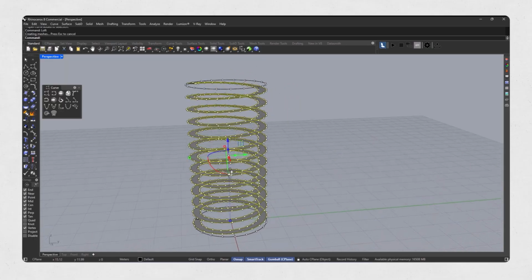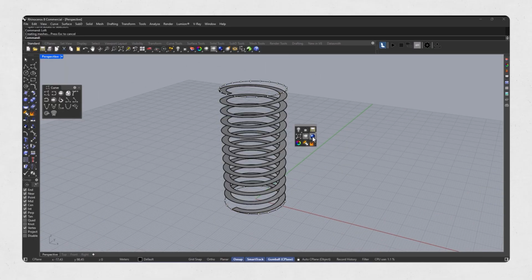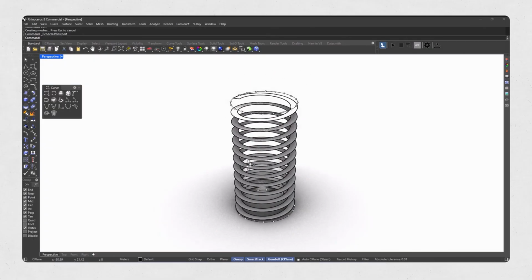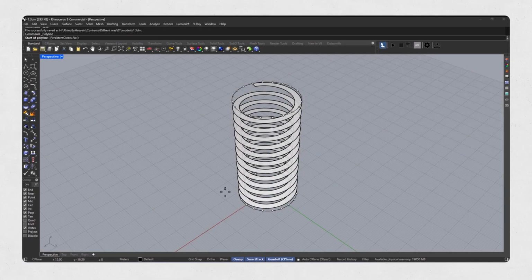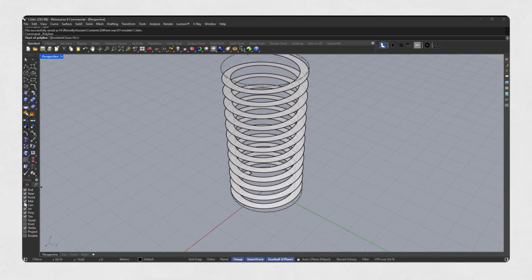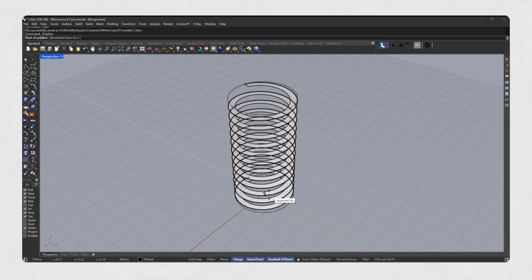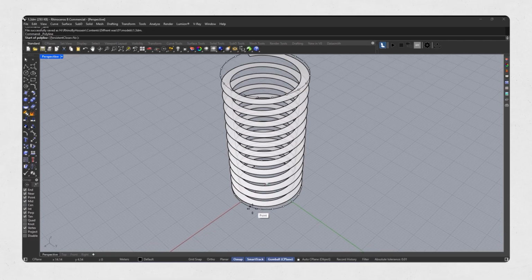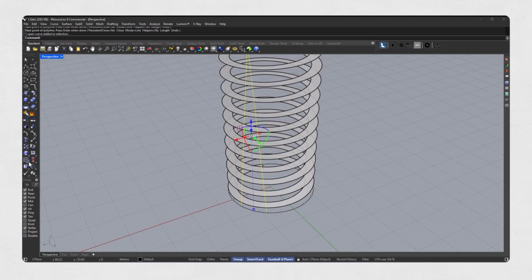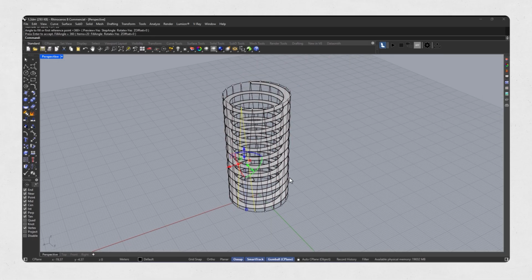Modeling the outer structure, we'll model the exterior wall using 3 different methods. Method 1. As shown in the image, I start by creating the first element using the points we generated earlier with the divide command. Make sure OS snap point is on, so you can easily select the points. Next, using arraypolar with the center of the base circle, I replicate this element 20 times to form the perimeter grid. Now let's shape the form.